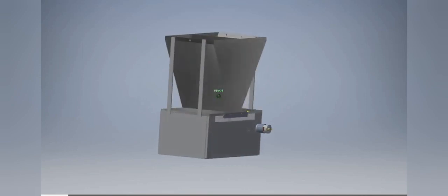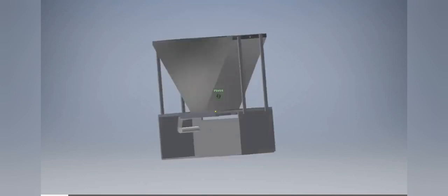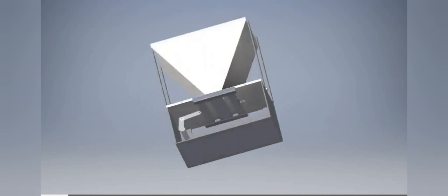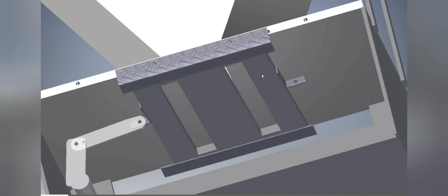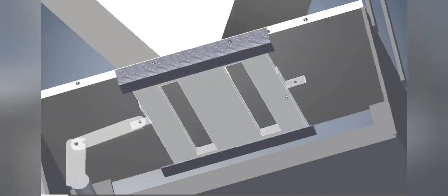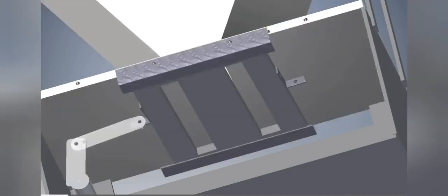Under the dispensing unit, we have implemented the slider crank mechanism in our 3D model. Now we will see how the slider crank mechanism is implemented in our system. We have used the DC motor as the only actuator which runs all the loads in our model. Here, the shaft of the DC motor is extended by means of a nylon rod. Again, this nylon rod is connected to the 2 acrylic connects, and these 2 acrylic connects are connected to the slider plate. This slider plate is mainly made up of foam sheet, above which there will be a sheet metal coating to enhance the sliding of the slider plate over the surface of these two L clamps.